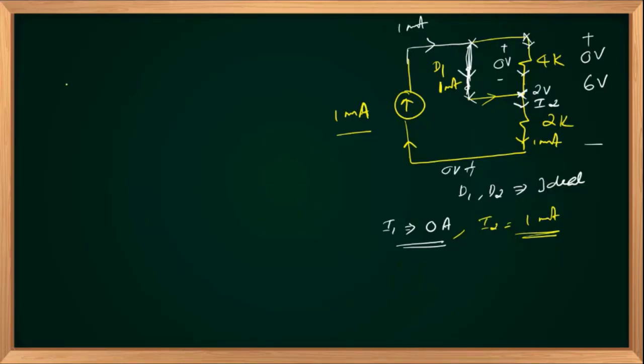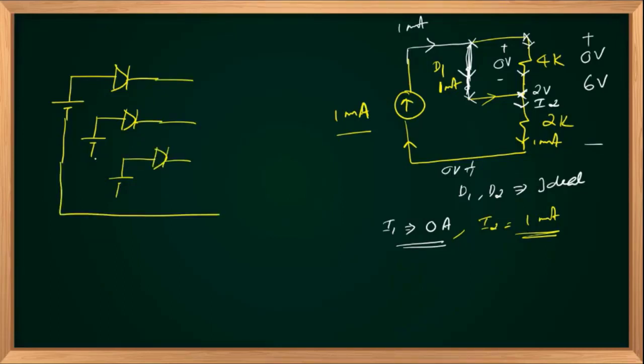Let us get into another problem that is a common problem asked in competitive examinations, that has 3 diodes connected like this. Reference voltage is the same. All cathodes are connected together and a resistance is inserted here. This is the V out. This is R. Let us assume this is 3 volts, this is 2 volts, this is 1 volt. You are asked to identify the V out. How much is V out?